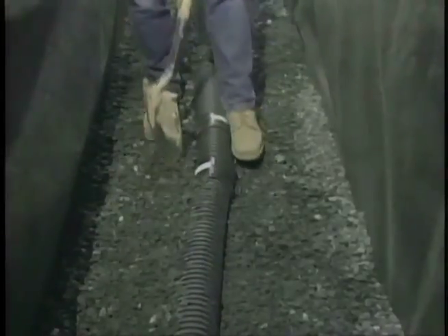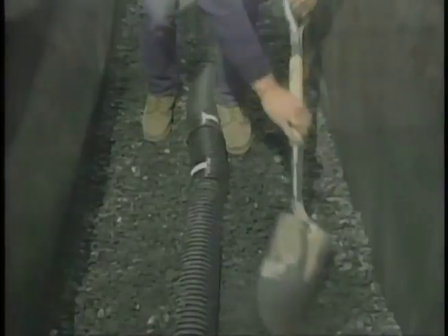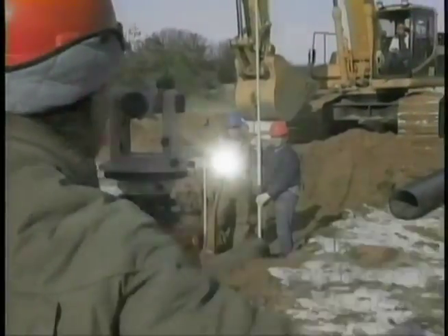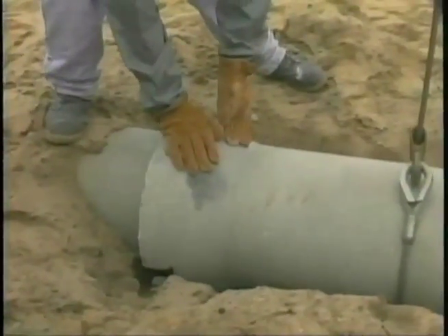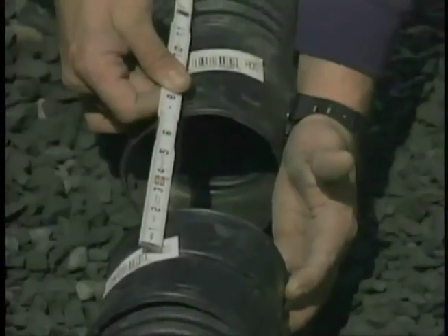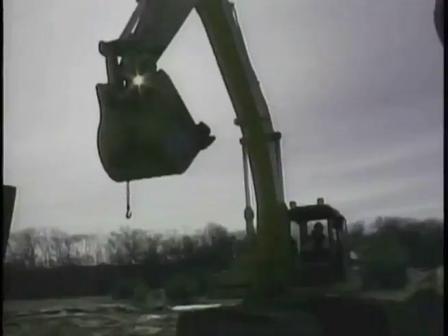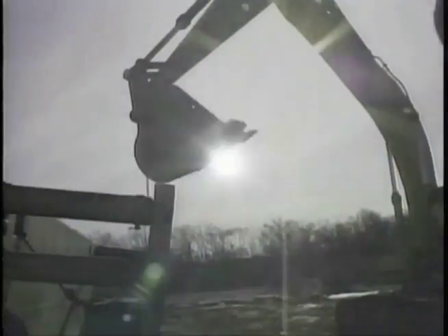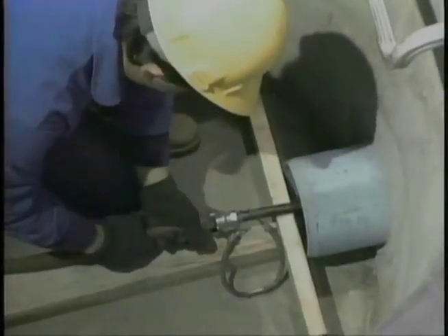There are no formal testing procedures for perforated pipes. The real test of these systems is how well a foundation resists dampness, mildew, and flooding, and how well the subdrain maintains the groundwater at the proper level. For any gravity flow system, whether sanitary sewer, storm drain, or a subdrain system, always refer to local plumbing codes and job specifications. Following the proper procedures will ensure a long-lasting, efficient installation.